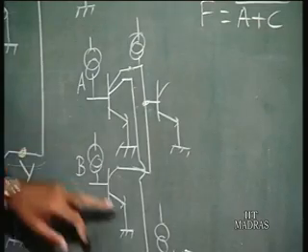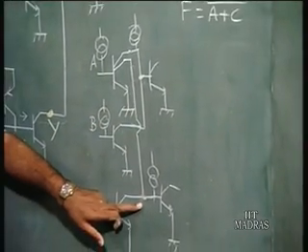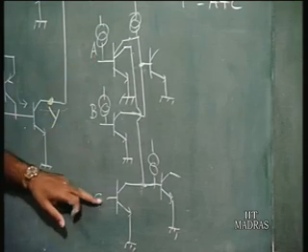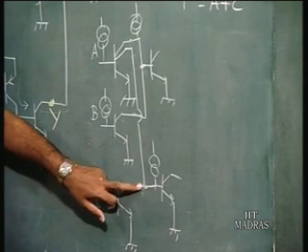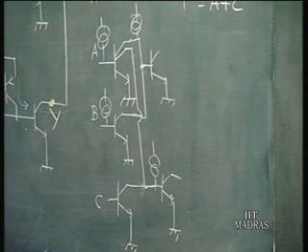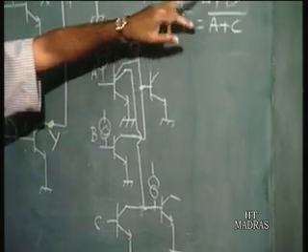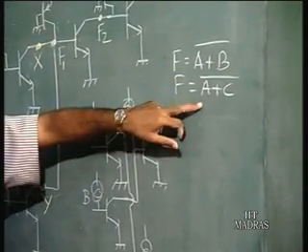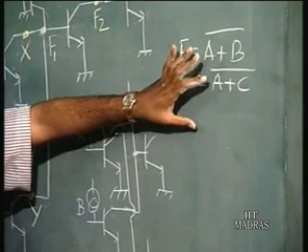So, here at this point you have just shorted these 2. At the inputs you have A and C. So, this is going to be NOR of A and C. So, using multiple collectors, if you want to have logic functions derived using the same inputs, you just require multiple collectors.